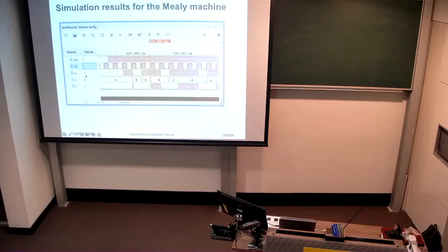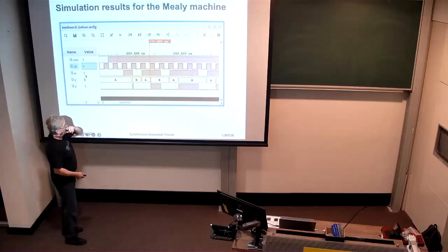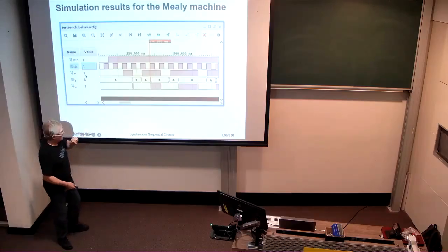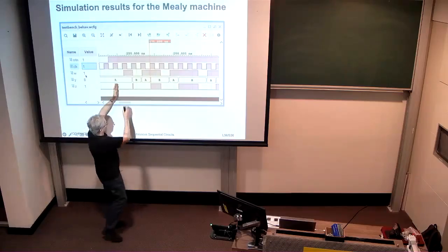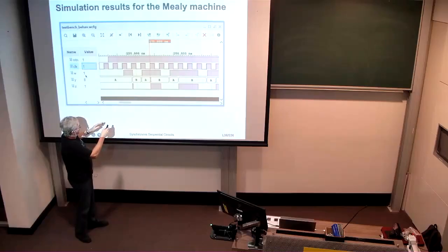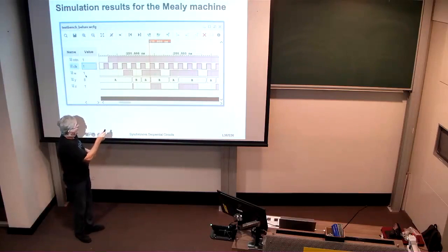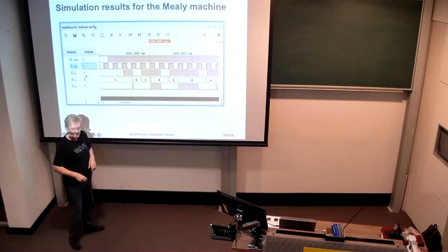Good. Seems like I've managed to convince you. Here's the simulation of that design. Now, this is a little tricky. Here we see the input is just slightly delayed from the active clock edges. So W becomes 1 just after the rising clock edge here, and therefore, given it's active for a whole clock period, it's high when the next active clock edge comes along.